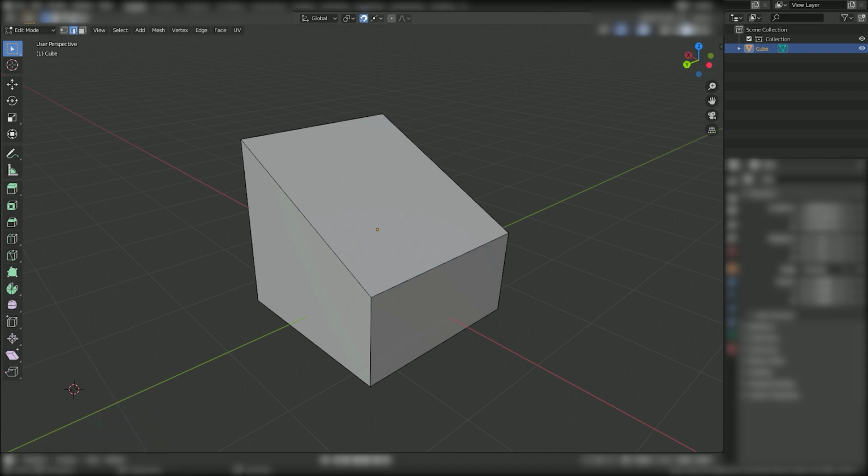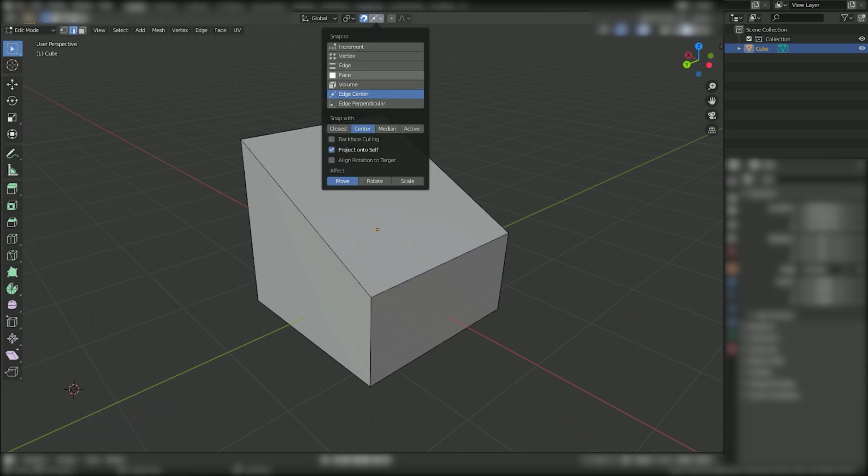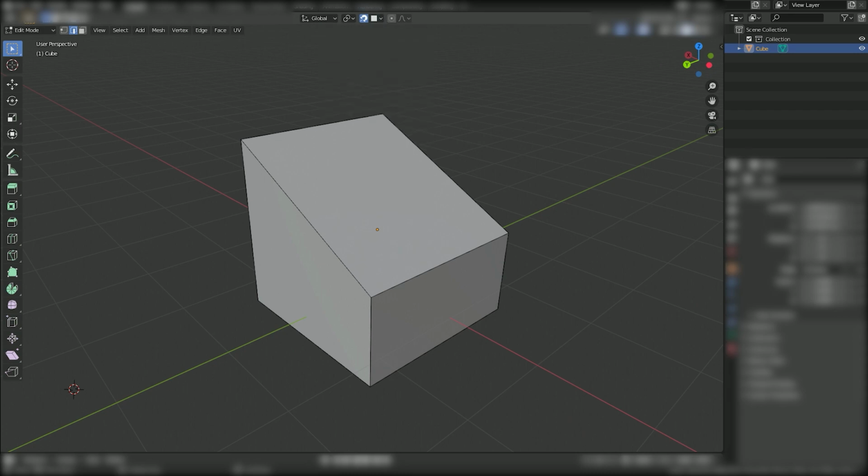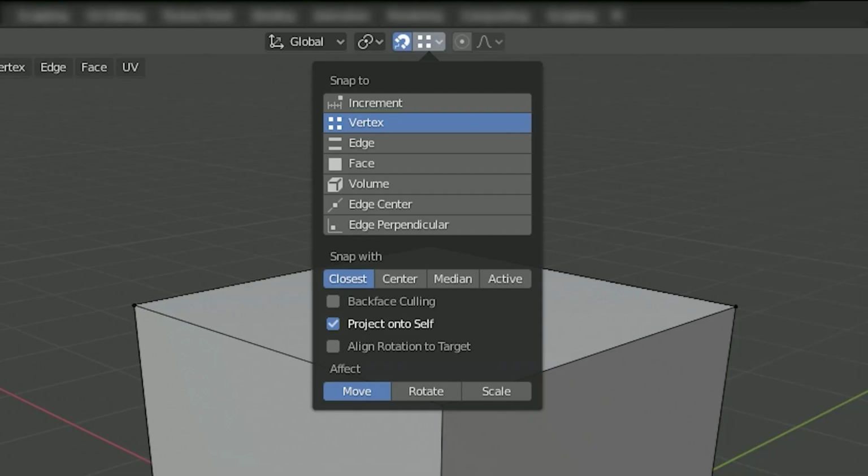Lastly, you can choose which transformation snapping will be enabled for. For instance, you can snap when rotating a face, but not when scaling a face, or the other way around, or enable it all the time by holding the Shift key and selecting all the options. With different combinations of these options, you have a ton of control of what and when to snap in your model. It does take a few more clicks than in SketchUp, but again, you have a lot more control and options to do exactly what you need.